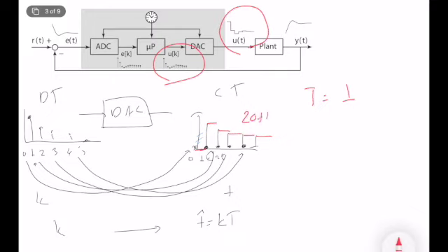Okay, so we will slightly cover first order hold. I will just mention it. I will not cover it in detail because in microcontroller algorithms, zero order hold is dominantly used in almost any system. In order to apply higher order hold operators such as first or second order hold, first it needs significant hardware improvement in the system, and second, it really doesn't bring anything useful.